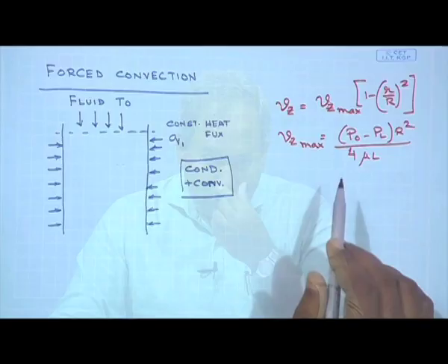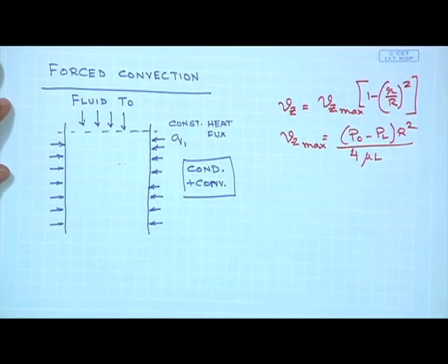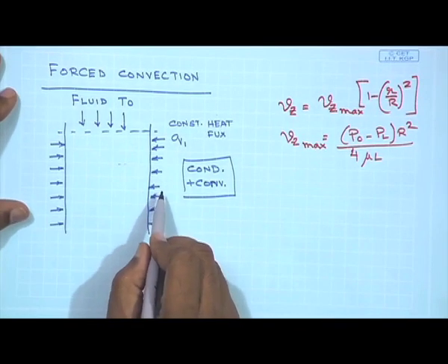If the physical properties rho, Cp, mu, etc. do not remain constant, then there is going to be a two-way coupling and a simultaneous solution of heat and momentum transfer has to be done to arrive at the expression for velocity as well as to find the expression of temperature. So, looking back at this figure once again, since it is a case of conduction and convection